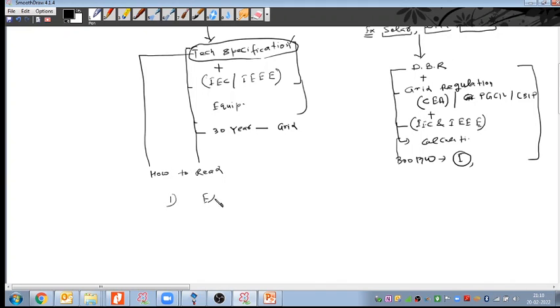the electrical design criteria, right? In the electrical design criteria, they tell about the voltage: the nominal voltage, the rated voltage, and other types such as impulse voltage, switching voltage, power frequency over voltage, creepage distance, right? And the frequency, what frequency we are going to follow.